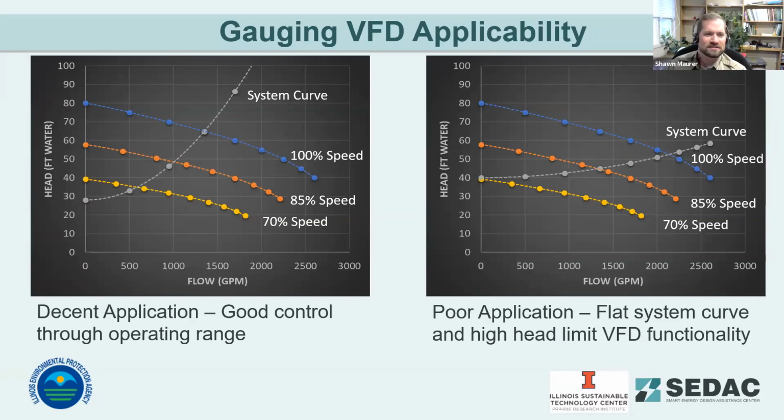So our poll results here, looks like most people caught on, especially since I went over it right before the poll question, but flat system and pump curves are not going to indicate a VFD is a good application. All those others, if you've got lower static head, you're going to have wider turn down capability. If you've got significant variation in flow from your design point, that's the optimal time to have a VFD. Longer run times are also going to improve the payback period for a VFD. So looks like most people caught on to that.